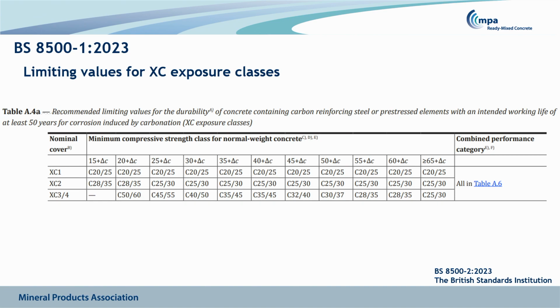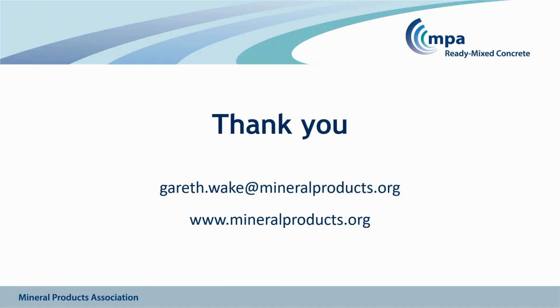Now, the thing to note with this is that for a particular strength, for XC34, cover depth has increased slightly. It's just something to notice. But I think it's particularly important, certainly as you move towards lower cover depths, that we have adequate strength to be able to provide adequate carbonation resistance. Okay, and I think that's it for me.